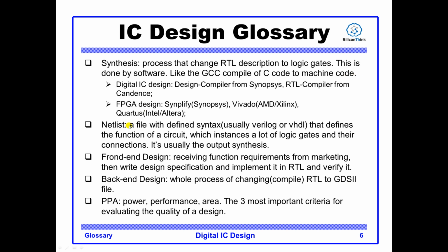Netlist. A netlist is a file with defined syntax. You usually use Verilog or VHDL syntax that defines the function of a circuit. In a netlist, there is only cell instances, only logic gate cell instances. This file is usually the output of synthesis.